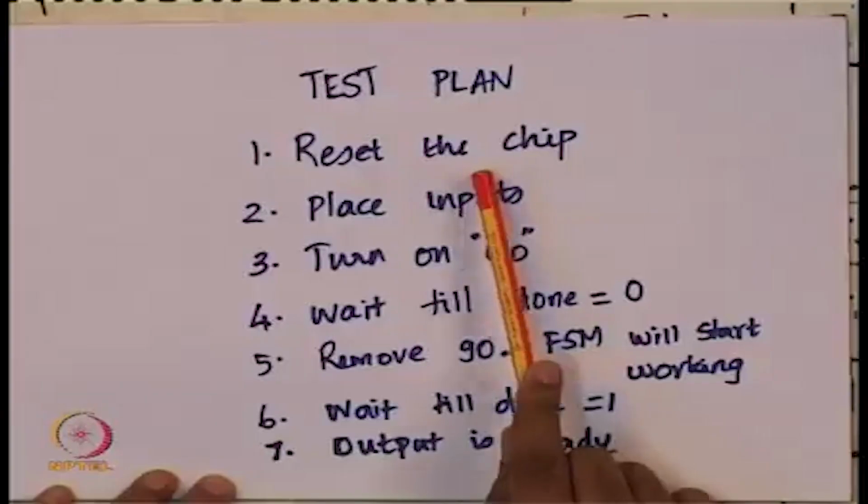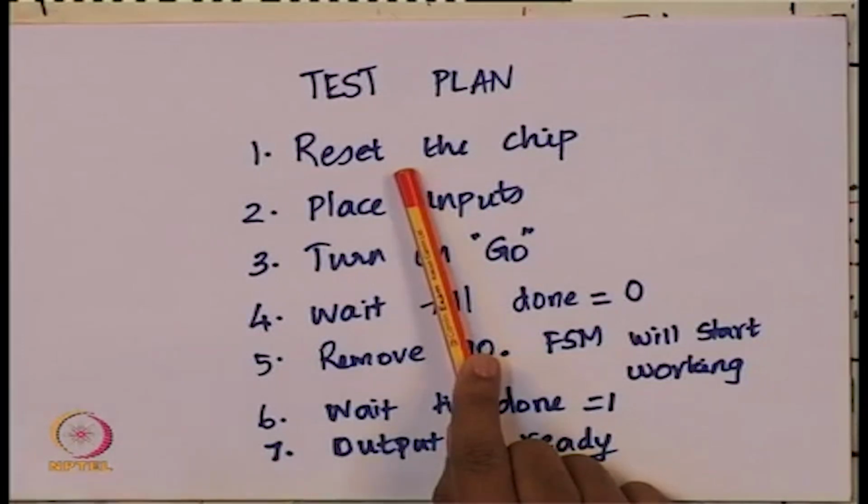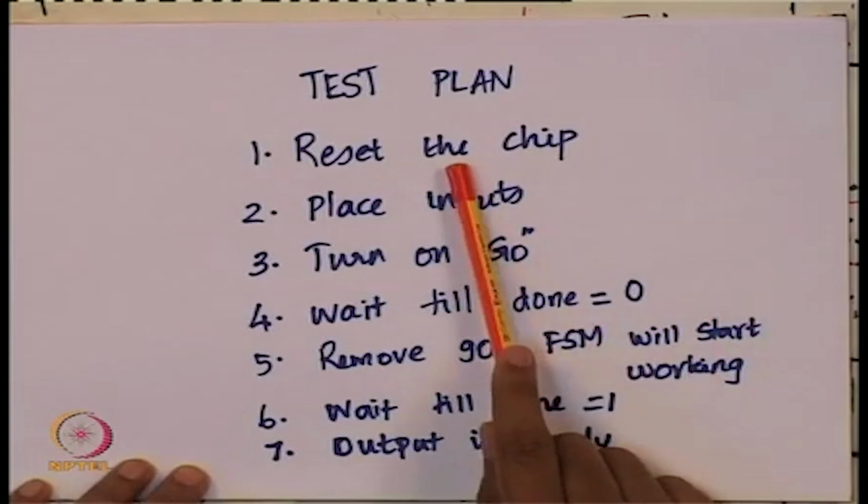So what I have done is I have written down a tentative test plan for testing this particular design. The test plan is like this. I will start with resetting the chip. The first thing that we need to do is reset the chip, because if the chip is not reset, then it is not expected to work anyway.